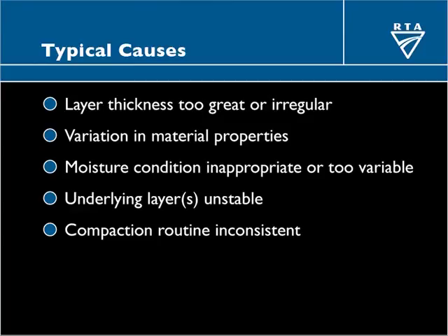It may be your compaction routine is inconsistent. That is unfortunately very common, either because the rollers aren't tracking properly, or because for some reason, maybe to do with construction traffic, they're just not covering every area. And that will give you variable results because the compactive effort is not the same, even if everything else is okay.